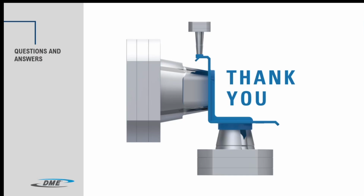Jeremy, maybe, or Ditty? Sure. So both the S-core and the DuraCore are expected to be dismantled during standard mold preventative maintenance periods. And both cores do need to be greased during that preventative maintenance, but that's it.